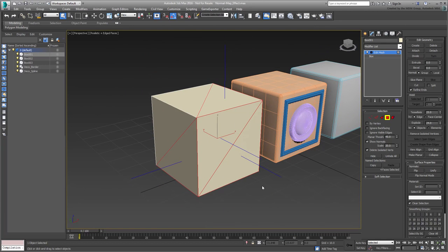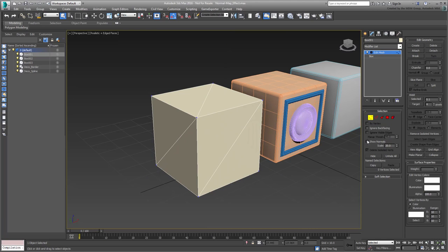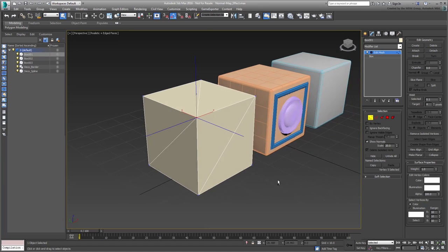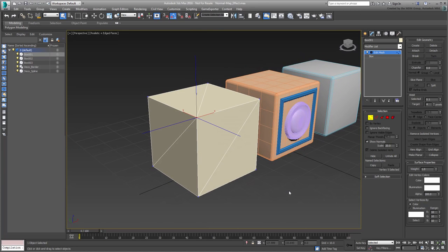In 3ds Max, you can also study the normals on vertices. Switch to Vertex mode and make sure Show Normals is enabled. Select the vertex at the top of the box. Notice that this vertex has 3 normals shooting in 3 different directions. In a way, this is expected as this vertex is common to faces shooting normals in the 3 same directions, but there's more to it.